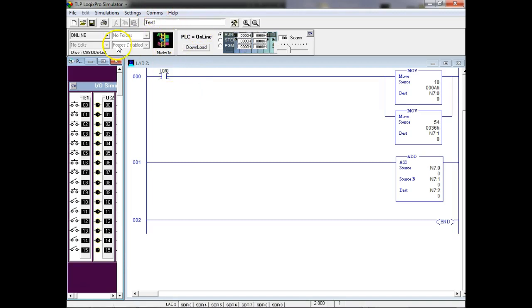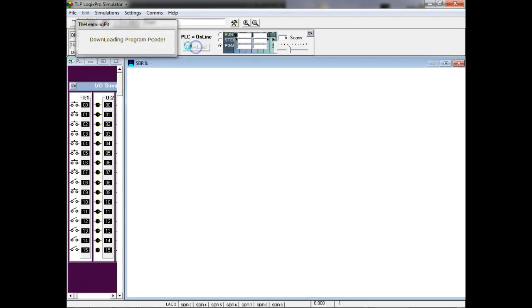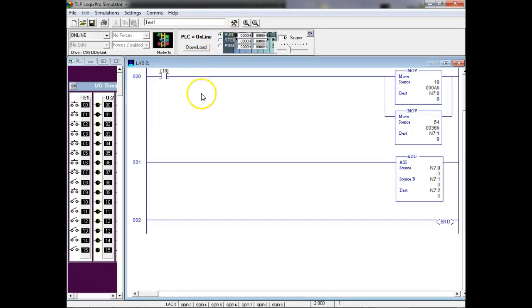Yeah, thank you. I used an input address that we would use on the other PLC, so I'm getting confused between the two PLCs. What input address should I have used? Yeah, I was just seeing if y'all were paying attention. So let's use input colon 1/0, right? I'll re-download it and then we'll switch to run. I'm on the wrong PLC.